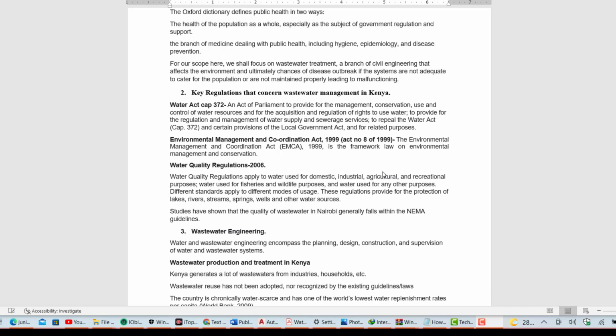And then the other thing that I've observed in Nairobi is the challenge of when water is being conveyed from the source to the user, because of congested systems, that is the stormwater system and the potable water conveyance system. And these systems have not been refurbished or redesigned for a very long period of time. So you find that there is mixing. And this is the reason why drinking water, tap water in Nairobi can be very dangerous for your health.